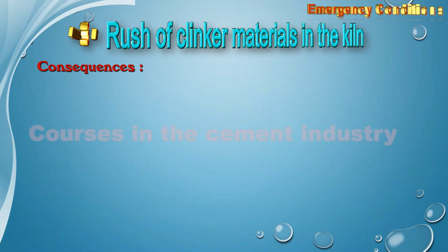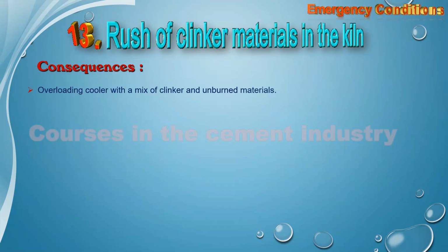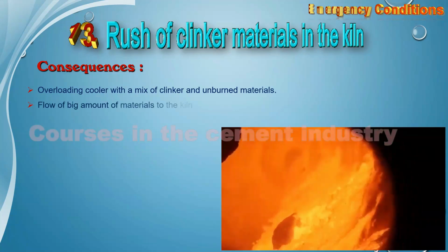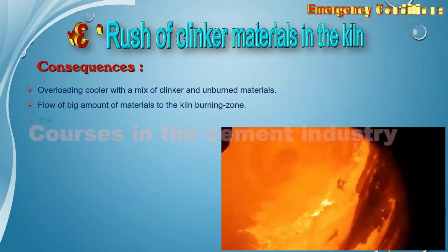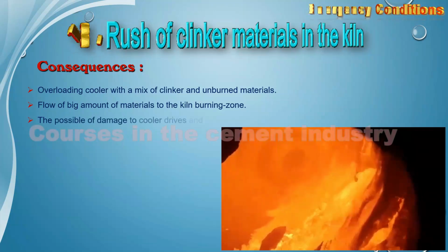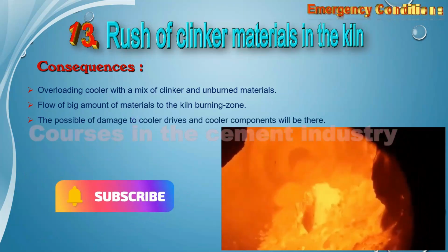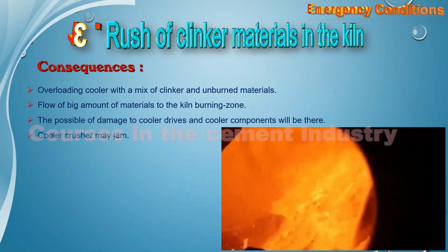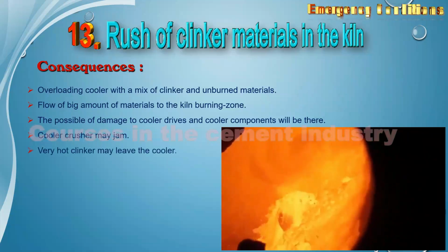Consequences. 1. Overloading the cooler with a mix of clinker and unburned materials. 2. Flow of a big amount of materials to the kiln burning zone. 3. Possible damage to cooler drives and cooler components. 4. The cooler crusher may jam. 5. Very hot clinker may leave the cooler.